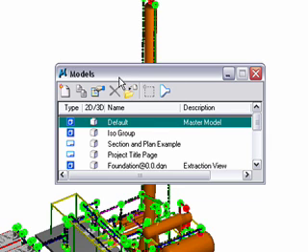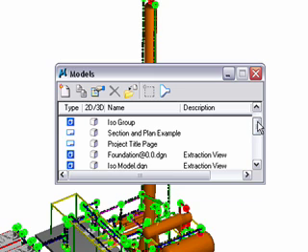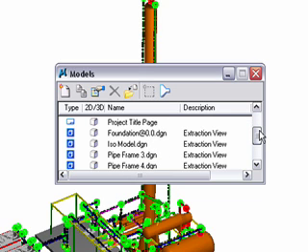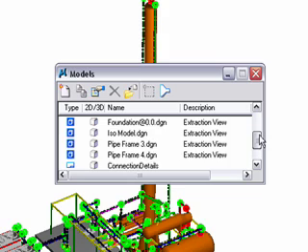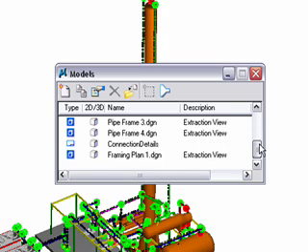First thing we need to do is open up our models, and that will open up the models dialog. Inside our models in Bentley's BIM solutions are essentially the drawings and information that can be stored within the DGN file itself. So you can see here that I have a number of models that I've broken out, and I can reattach these as and when I want. So I have foundation models, ISO models, piping, connection details, framing, etc.